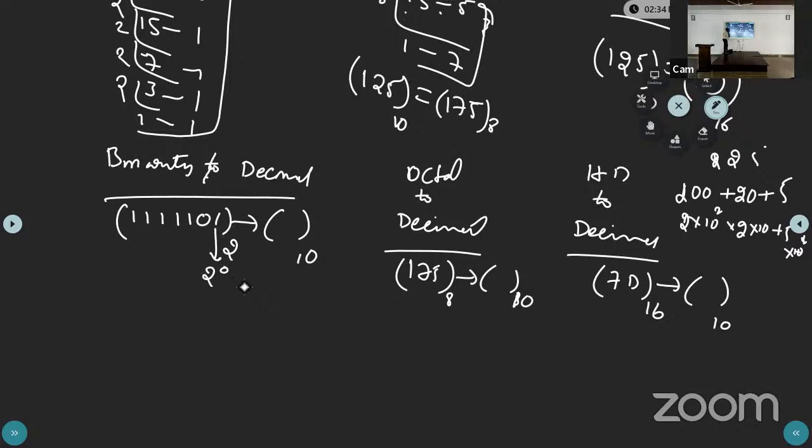2 to the power 0. And this power weight value is 2 to the power 1. Similarly here, what is the number system? Decimal number system. Take 325. Here 3 into 10 square, 10 square is the weight, 10 is the weight, 10 power 0 is the weight. Similarly, here also same. Now this weight is 2 to the power 0, and this weight is 2 to the power 1, 2 to the power 2, 2 to the power 3, 4, 5, 6, 2 to the power 6. Now you can multiply and add with the weights of the binaries.